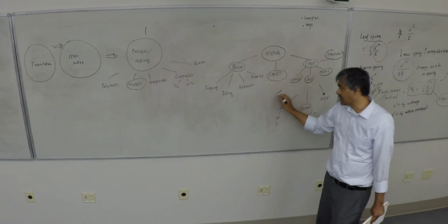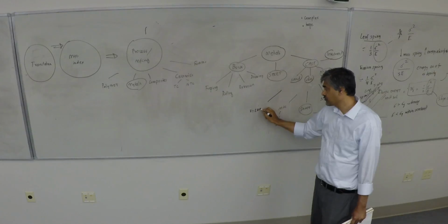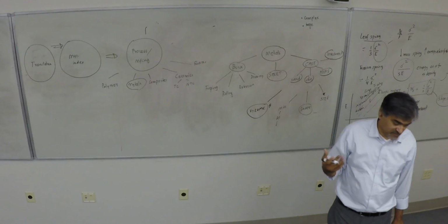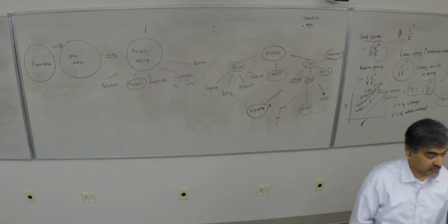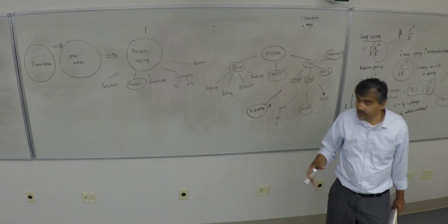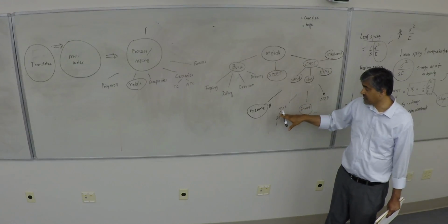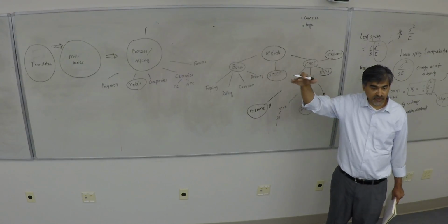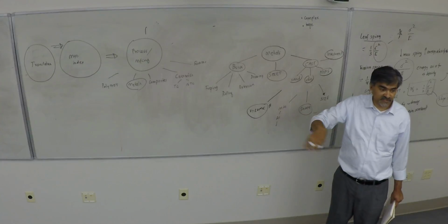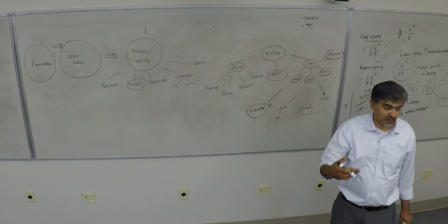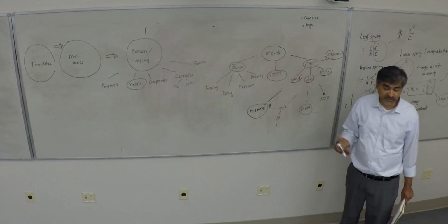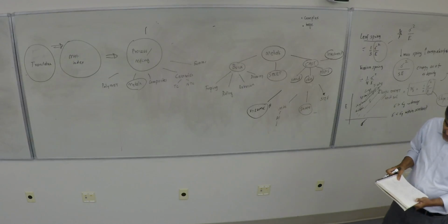The other big thing that becomes a factor is volume. And this I mean is volume in terms of numbers, not in the size volume, right? If you want to make 5 parts, or you want to make 50 parts, or 50,000 or 5 million parts, that's going to change your selection completely, because now a lot of other costs that would factor in start becoming less and less as the volumes go higher and higher. So you have a break-even point for every design, at which point one process starts becoming more economical over the other process. So that is the beauty of scale, I guess, the scale in terms of volume. So that is to be noted here.